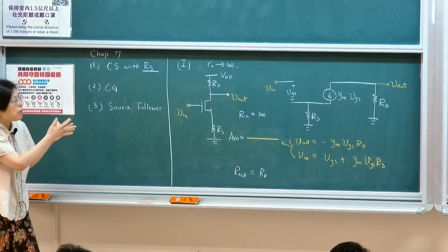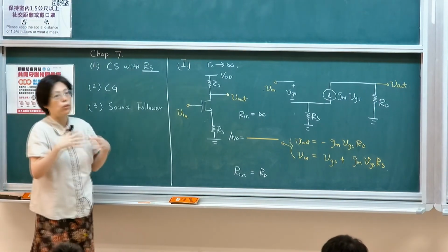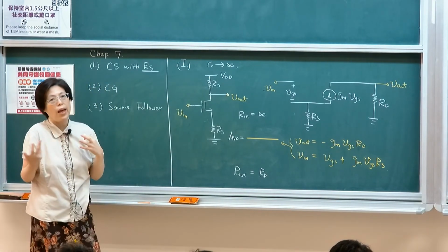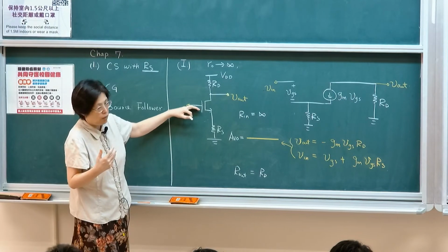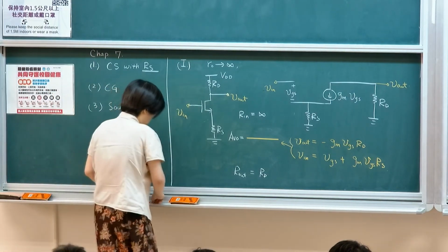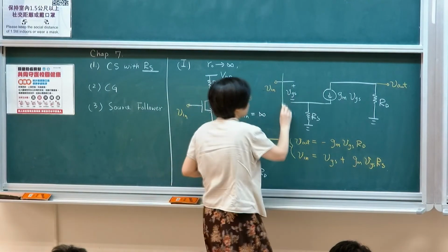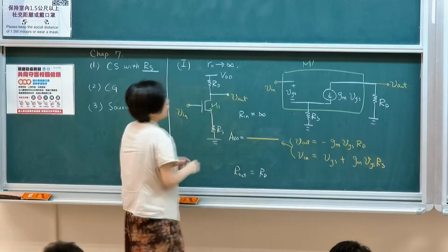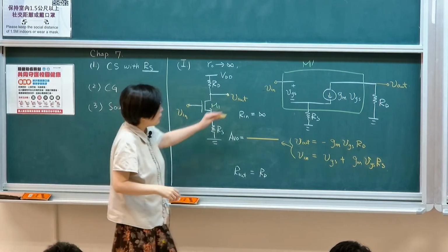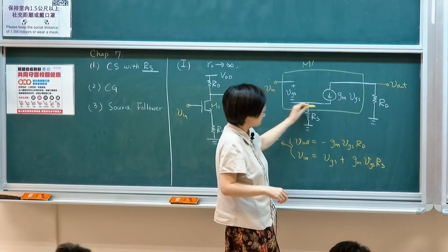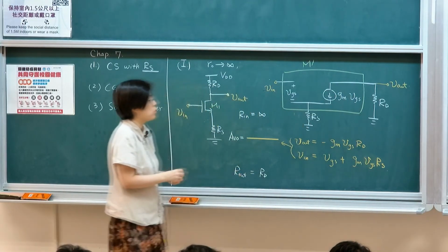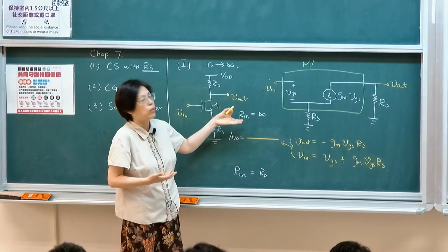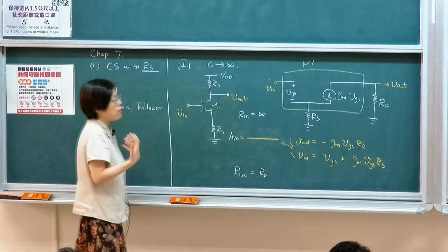If you have this typical circuit, the first principle is that we ignore the channel length modulation effect, meaning you assume an ideal current source when this is on. So this would then be my small signal model. This will be M1. My input is at the gate terminal, the output is at the drain terminal, and there is a resistor stacked at the source terminal. When we talk about input resistance, this is much easier, because anytime you come in from the gate, the resistance itself is infinite.